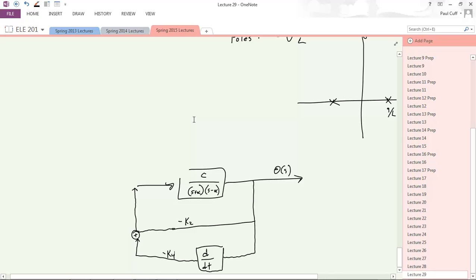Okay, that's awesome. It's interesting that we just linearized. So when it gets too far off, the math isn't quite correct anymore. But as long as it stays in its equilibrium, and that's how a lot of control is done. A lot of control for flying a rocket or a space shuttle, or even a military fighter, they linearize around where they want it to be, and they just have to make sure they stay in that region for the control to work. Thank you.